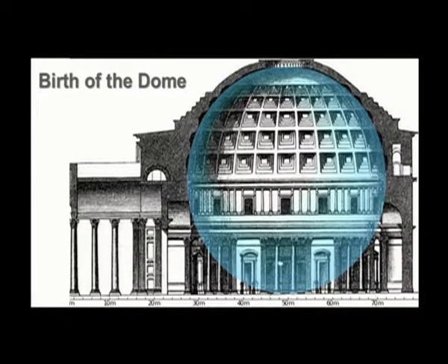But then what really happened in this place is, if you could see this diameter of the top area, the oculus is, like I said, approximately 11 meters. Just like in an arch construction, the topmost point is something called a keystone, where you put the keystone and lock everything into place. While they construct an arch, they make a frame, called a centering, and the centering needs to be in place until the keystone is placed on the top. The moment the keystone is placed and the arch is locked, you can immediately take the centering off, because the arch then becomes a completely self-supporting structure.